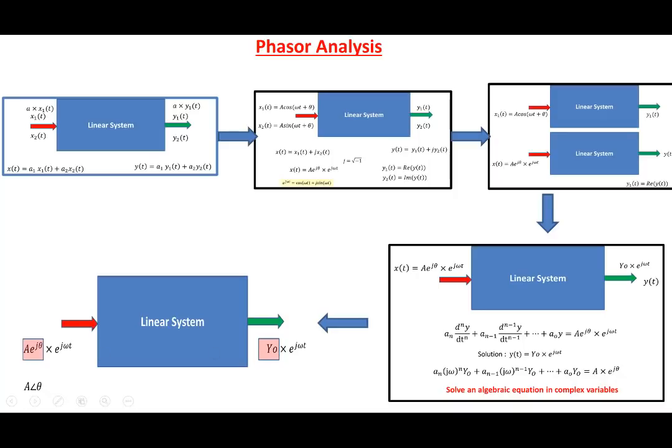So in the next lecture, we'll see how each one of those elements, R, C, and L, can also be transformed into a complex element with a complex value. And then the circuit can be analyzed in terms of those complex variables, in terms of these phasors, and the phasors can be transformed back into the time domain anytime we want, by adding e to the power j omega t and taking the real value. All right, so let's stop here.